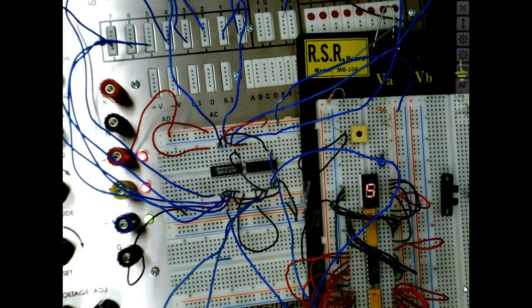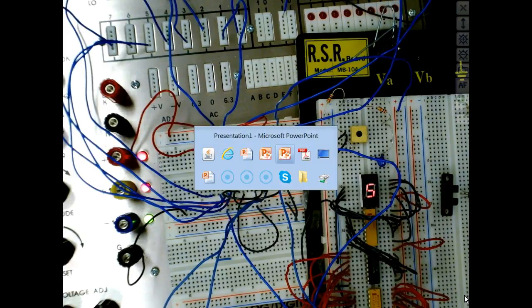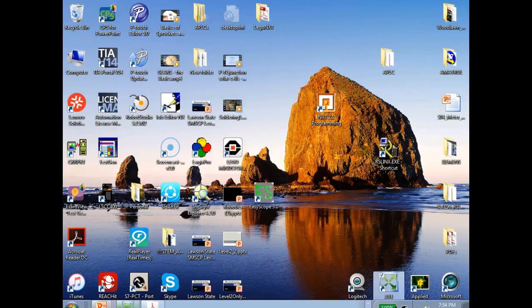So right now, I would have to scan that keyboard, but what am I doing with my keyboard? Nothing. So they came up with a method called interrupts. This computer never scans that keyboard, but when I hit a key, it generates an interrupt, and the processor will stop what it's doing and go to a certain place, which is defined in something called a PIC, which is a priority interrupt controller. So we can see the interrupts